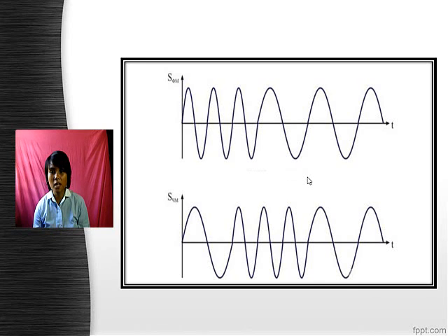The difference of phase modulation from frequency modulation is that the latter requires a frequency detector to receive a frequency modulated signal. In the case of phase modulation, you can receive a signal using a regular receiver with amplitude modulation. A small detuning on the receiver weakens one of the side bands so that an AM detector outputs a signal. One can also receive a modulated signal using single side band modulation receivers. Frequencies of the sound spectrum will be accentuated.